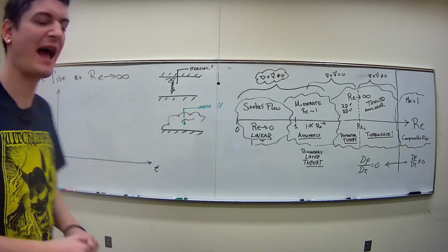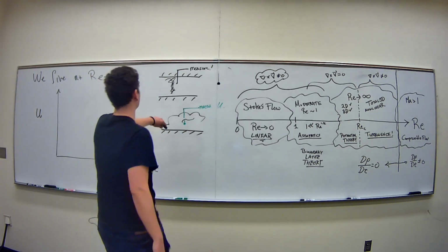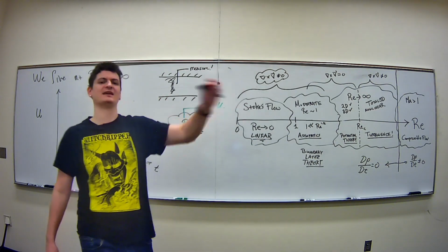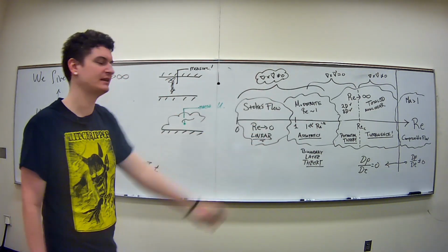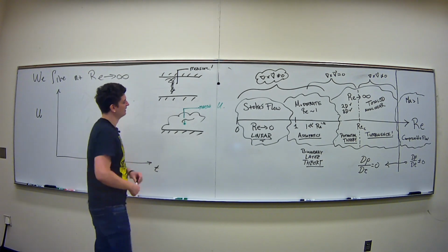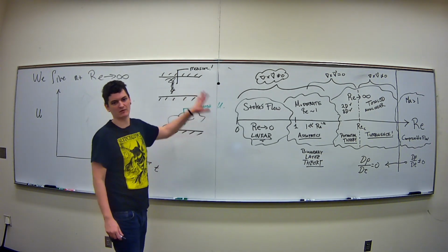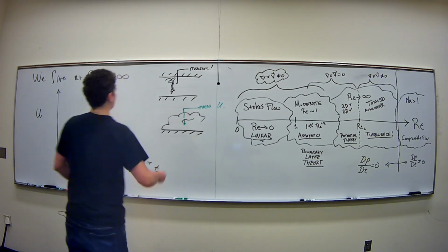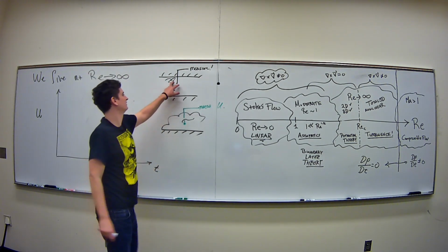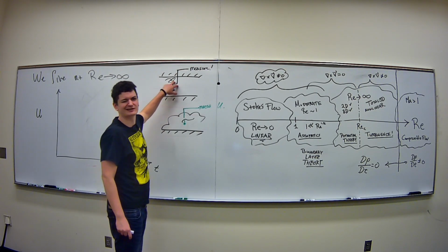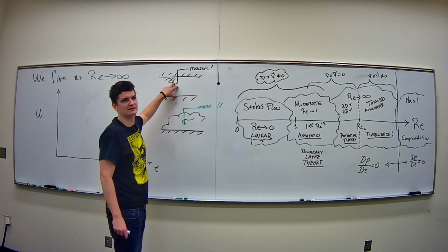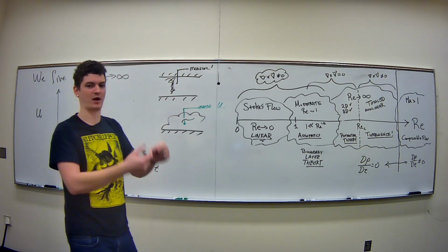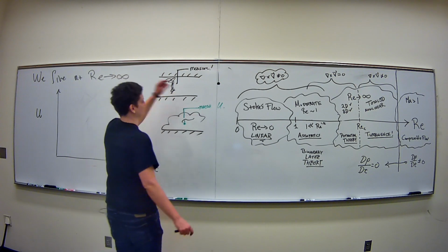I think now they use Doppler laser radar, laser methods, to figure out velocity at a point. I think you put reflective particles in the fluid, and then you shine lasers to get this velocity. But either way, you come up with some method to figure out what velocity is. It could be a Pitot tube, which you did with your first one, or you could do electrical methods, where you correlate a voltage value to the speed of the fluid, because it changes the electric properties based on how fast it's moving past your little probe.